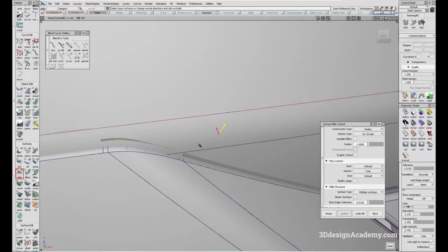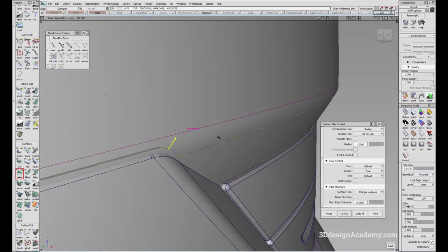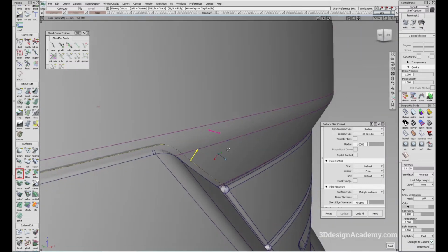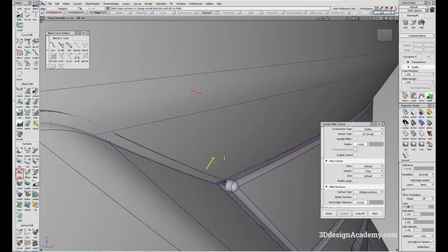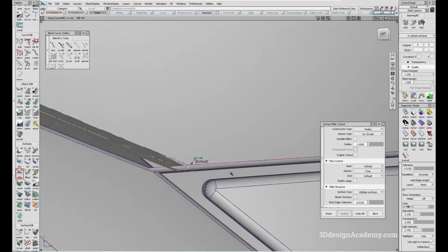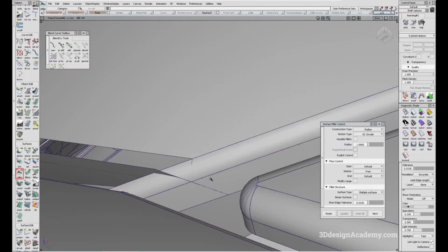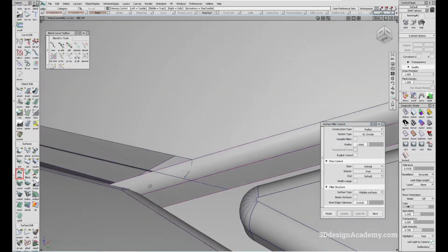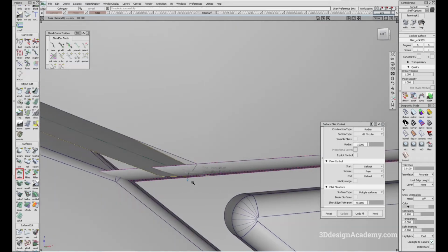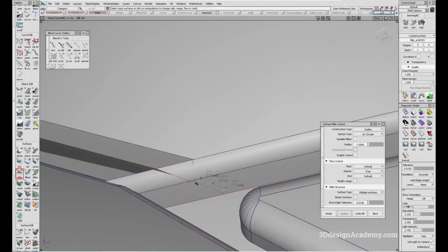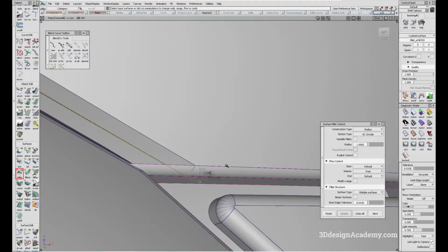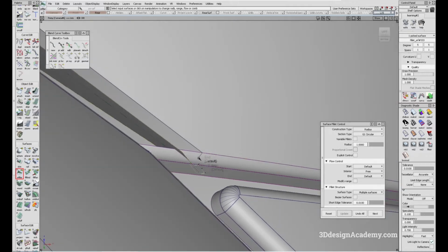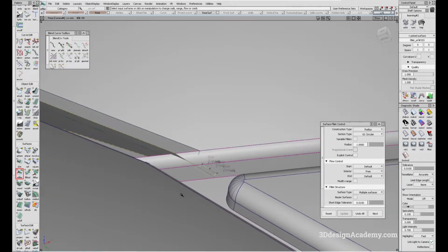And I'm just going to go down over here. Okay, it looks like this. Okay, there we go. Now I'm going to pause over here. I'm just going to put the fillet here like this. And this one does worry me a little bit because this is probably going to give me a triangle. And it's probably not going to make it. No, it doesn't. Okay, so if that's the case, I probably have to think of a different way to do the fillet. Either make one side bigger, or we can always make this a little bit smaller at 0.9.